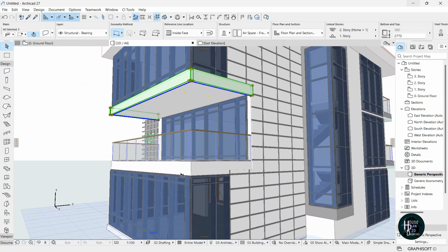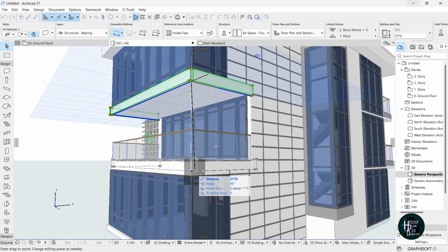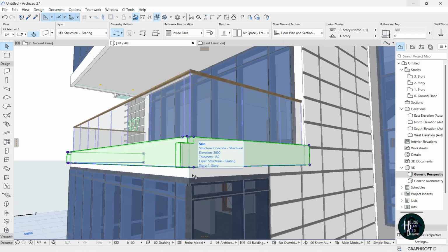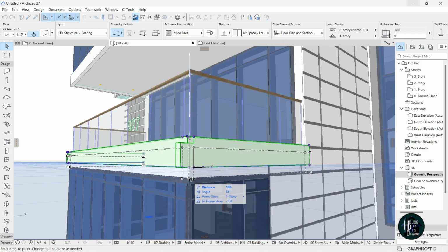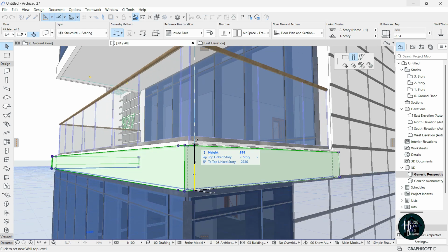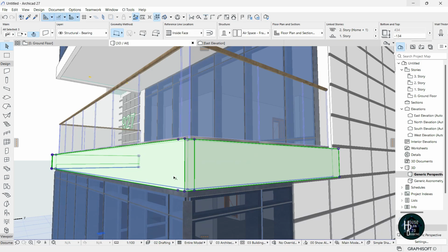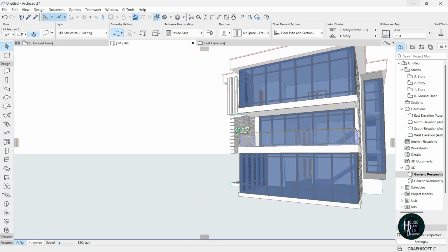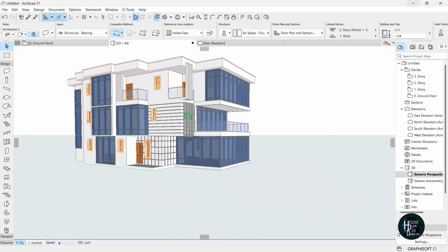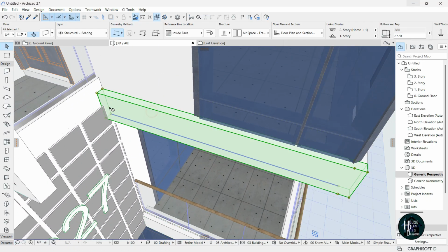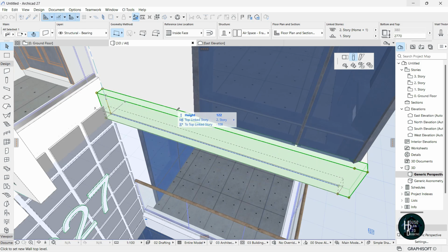Now do the same thing for this other side also. Press Ctrl Shift D, click this node here and move it downwards like this. Alright, now I want to come down a little bit also. Ctrl D and pick this side like so. Click this also and stretch it to that height like that. So you can have the design come outside like this. Now for this edge here, click this, click on this node here, stretch it like this.